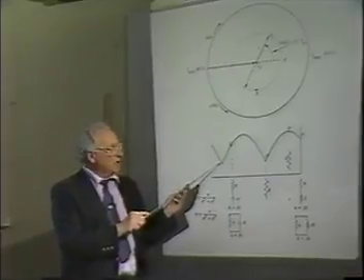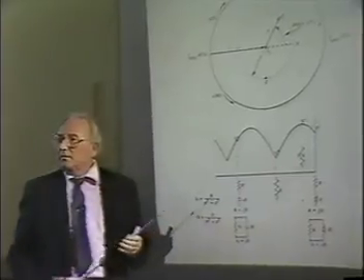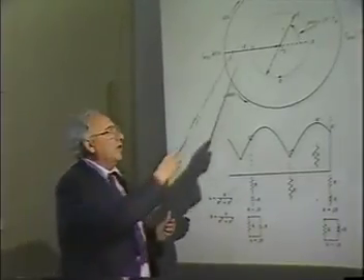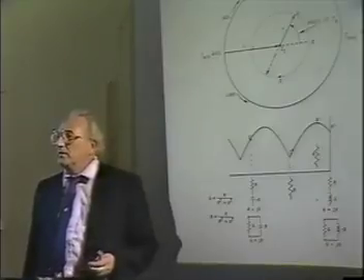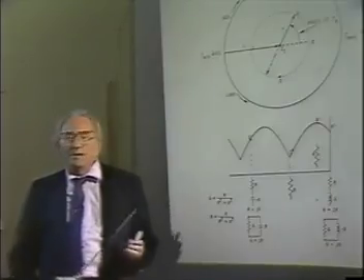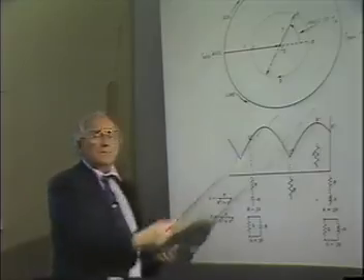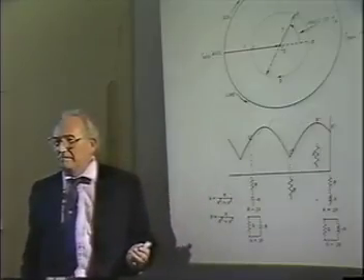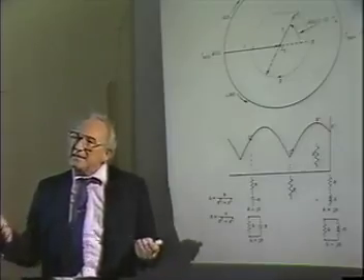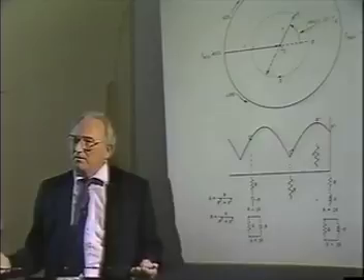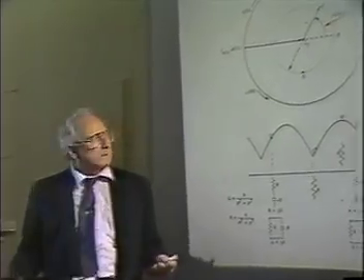You'd start here and you'd go around and around this chart until you get that many degrees, knowing that around the chart one time is a half wavelength. Around it again would be another half wavelength. So you guys have got to keep that in mind when you work problems. But it's going to be simple because the numbers are on the chart.